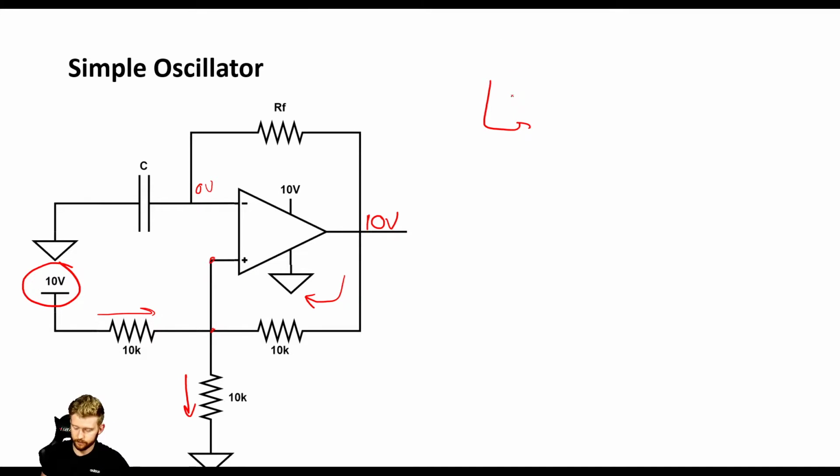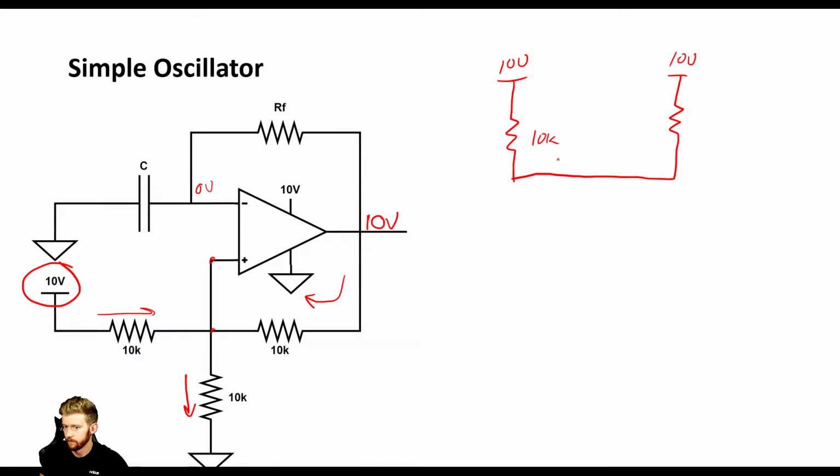So we start off with our 10 volts. We have this 10K resistor here. So that's that 10 volts there. And we also have 10 volts from our output. Oops, I forgot my resistor again. 10 volts from our output. Okay, and then those are tied together at this node here. And then there's also another 10K resistor to ground. So these are all 10K, and that'll become important.